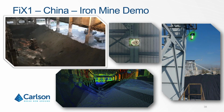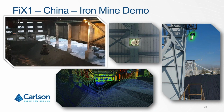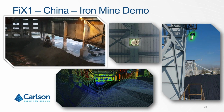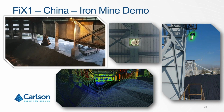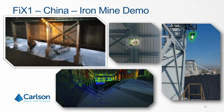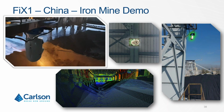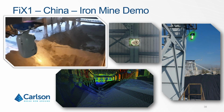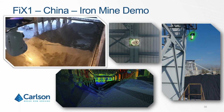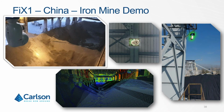The next installation, we had a couple of installations, is in China, an iron mine demo that we did. As you can see the results at the bottom that we got, they put a FiX1 over here as they're scooping out material, and they usually would have someone go up there with a total station to measure it every once in a while. So you can see they mounted the FiX1 permanently over top on one installation here. And on this one, for the test site, they created a temporary mount. As you can see, it's scanning over top of it. They also have one installed outside as well, scanning the coal piles and such. So this has been a big success in China where we have a couple systems, and it's been invaluable to them.